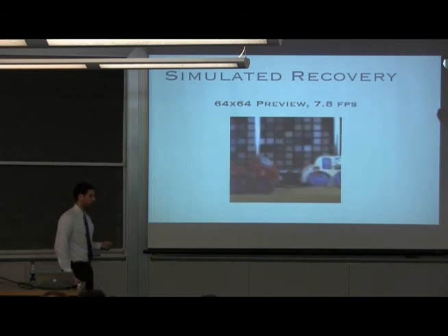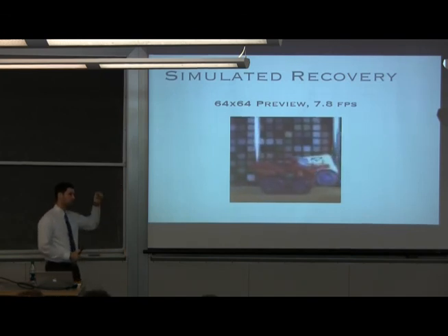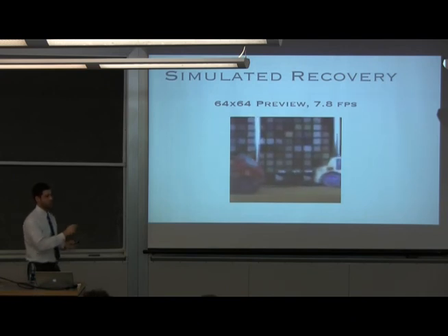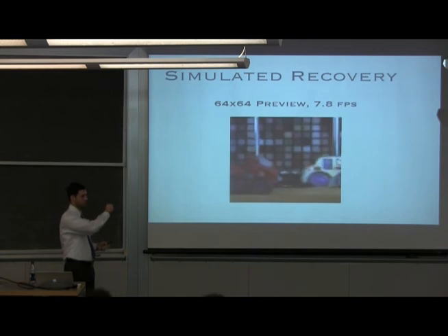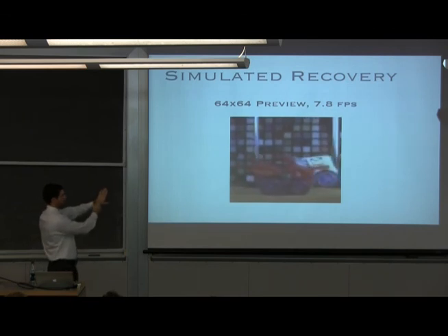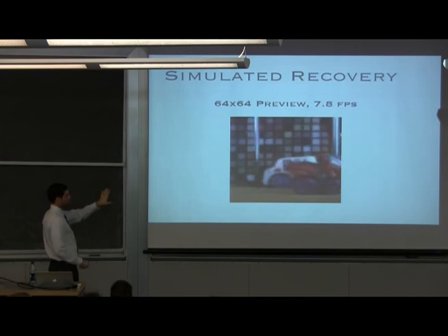The reason why is actually because we've only subsampled 4x4 blocks of the image. So what happens is if you look at those 4x4 blocks, they have 3 plus 1s and 1 minus 1 in the transform block. And every time you take a measurement, you change where the location of that minus 1 is. So if you have a vertical feature that passes through the image block, every other measurement is switching inside the transform where the minus 1 appears. And that causes the image features to shift back and forth a little bit.